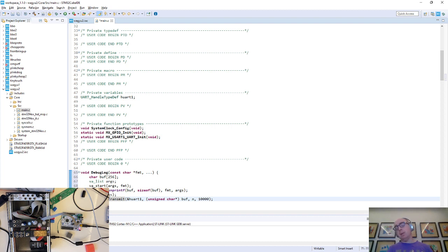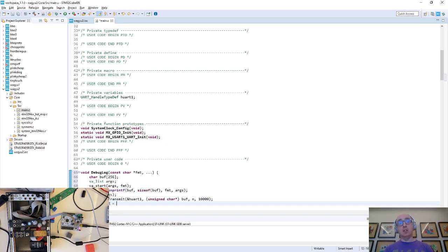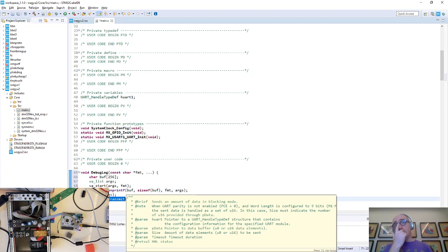The idea is that each chip actually has slightly different hardware. So they may change the registers underneath, and you can directly access the registers. So in fact, later on, we're going to be accessing the GPIO pins. And so GPIO port B is that, and look, autocomplete, it has a bunch of fields, and these are actually memory maps. So if I write to the output data register, I can literally set 16 pins at once by doing that. So 16 pins have just been set. So that's the low-level way of doing it. Or you use HAL, which basically abstracts it and gives you help.